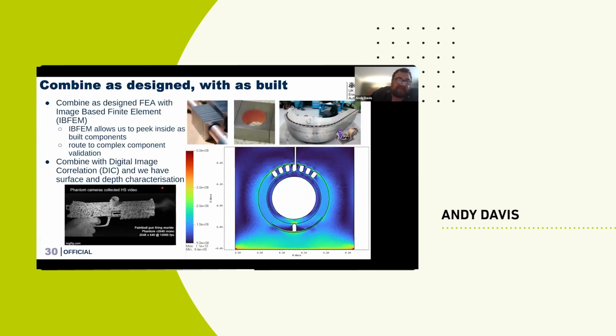We also have the need to compare against experiment. So we often want to compare what we've done. This is in the true engineering sense. We have made some physical asset and we'd like to understand what's going on. One approach is something called image-based finite element modeling. So we can take relatively small components. So this is what's called a divertor monoblock. These are each thermally isolated from one another. They sit on a copper chrome zirconium pipe, and they bend around this entire component.